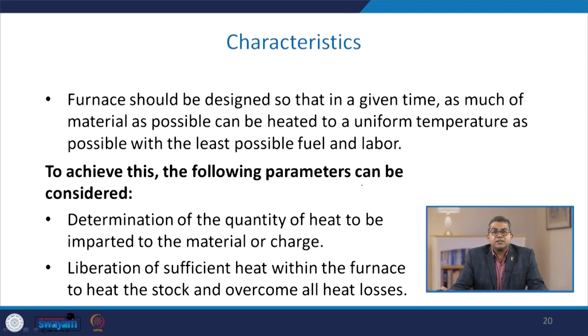To achieve this, certain parameters need to be considered. One is the determination of the quantity of heat to be imparted to the material or charge, which depends on the steam requirement, that is, how much temperature and what pressure you require. All these things are interlinked. Another parameter to be considered is the liberation of sufficient heat within the furnace to heat the stock and overcome all heat losses.